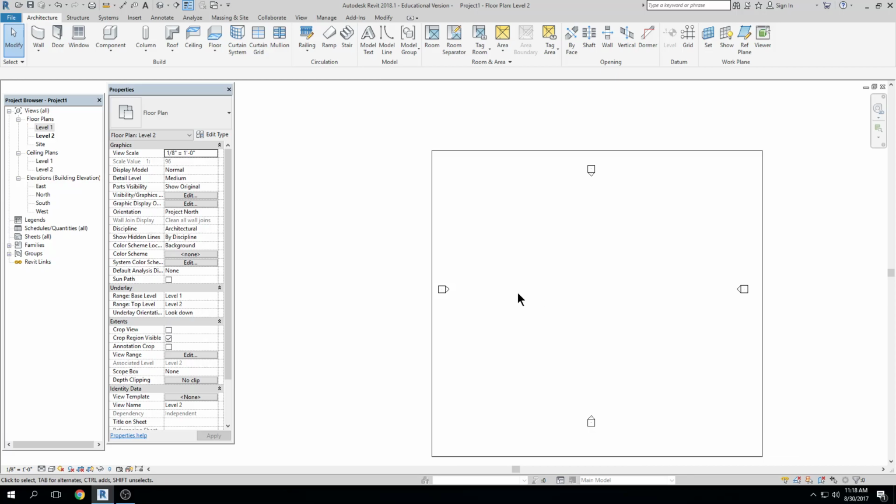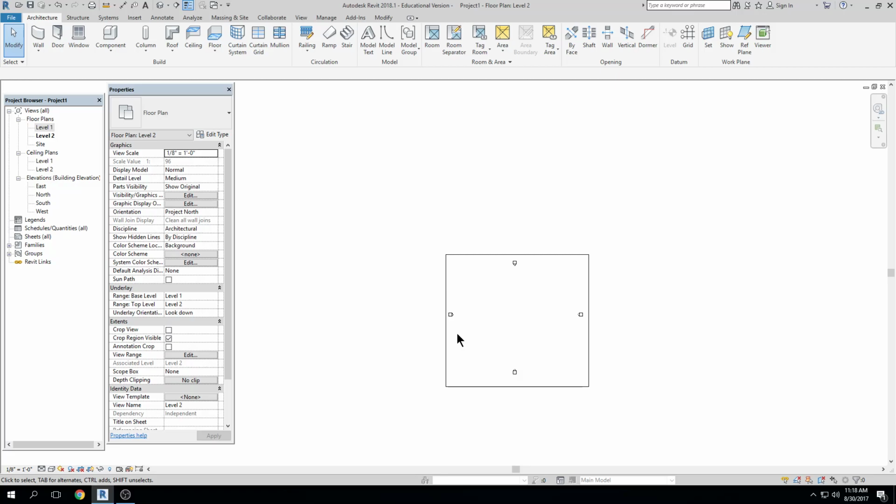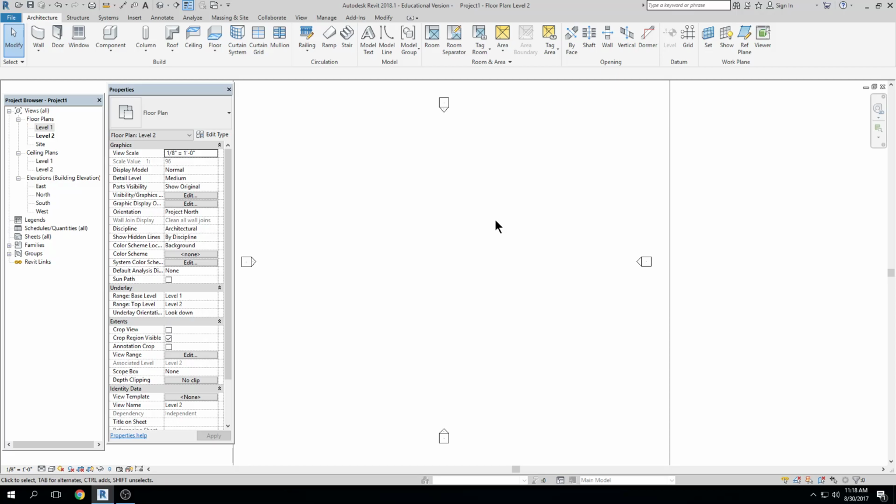I can also zoom extents. If I have this drawing and I've zoomed way too far out and it's all the way down over here, and I can't find my drawing, if I double click my middle roller twice very fast, click, click, it zooms to the extent of the drawing and brings it back on screen.